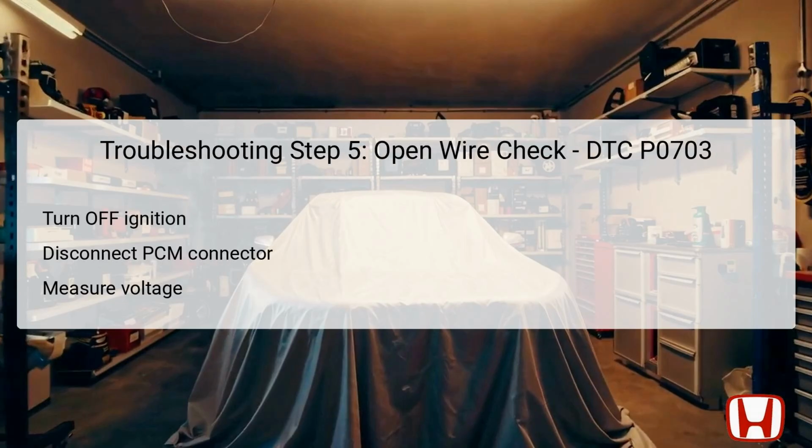Step 5 involves checking for any open wires in the brake pedal position switch signal circuit, referred to as BKSWNC. First, ensure the vehicle's ignition is turned off, lock. Once powered down, use the Honda Diagnostic System, HDS, to jump the SCS line and wait for more than a minute to allow the system to stabilize.